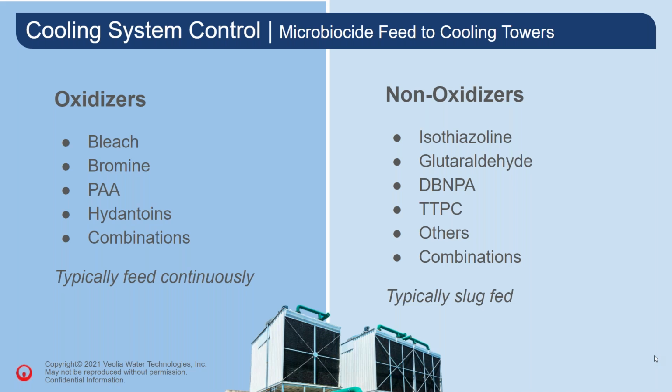So ensuring that chemicals that are used for one function aren't brought to the cooling tower and used as a biocide is important. As we said, the microbiological growth can lead to scaling by providing a seed site for crystal growth, corrosion by secretion of acidic byproducts, and fouling by their colonies and or mats.